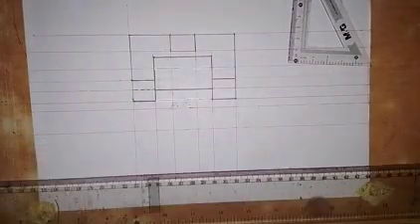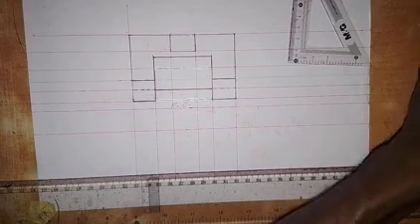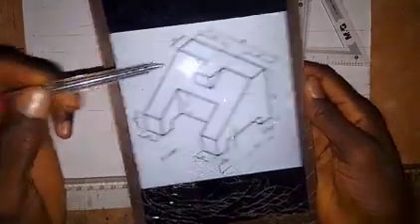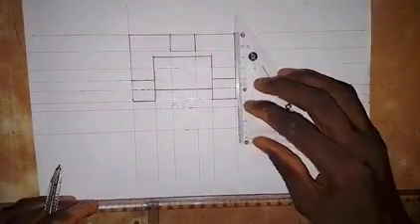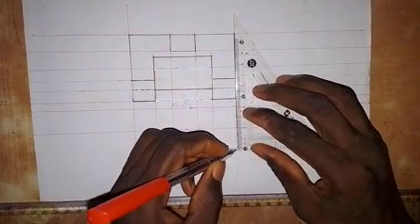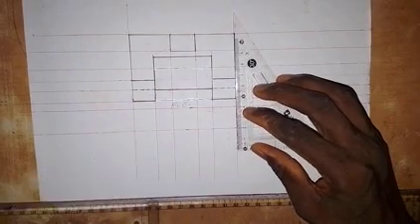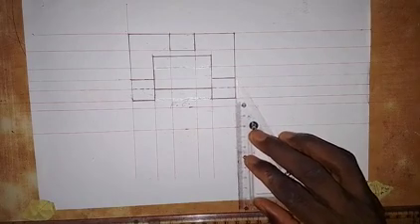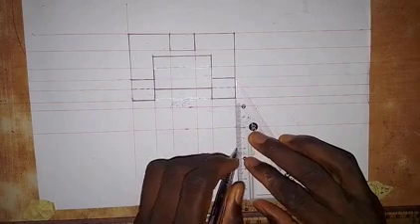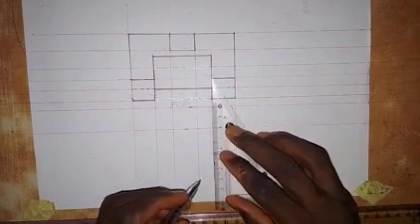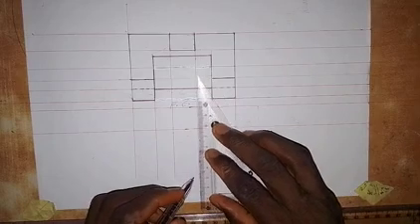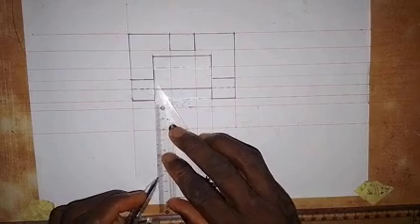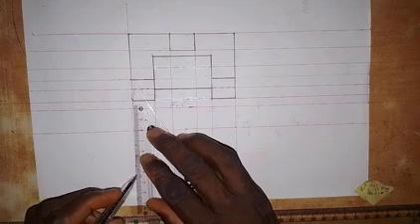There's another thing that we have here. The distance from here to here is also 20 millimeters. So I need to come down from here and take a measurement of 20 millimeters. So this is 20 millimeters here. I will need to extend this line because I still need 40 millimeters. So I will take this line down, also this down, this line down, then this line down, also this one, and then we also have this.